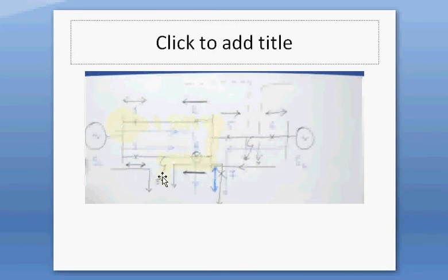So what we have observed in this case is that under normal working condition, the current from relay 4 is flowing from left to right, but now under fault condition, the current from relay 4 is flowing from right to left. Now the direction of current is reversed after the fault. So there is a need to place a directional relay at position 4, which will operate when the direction of current is given by this arrow, that is from right to left. Similarly, the same relay we need to place at position 2.